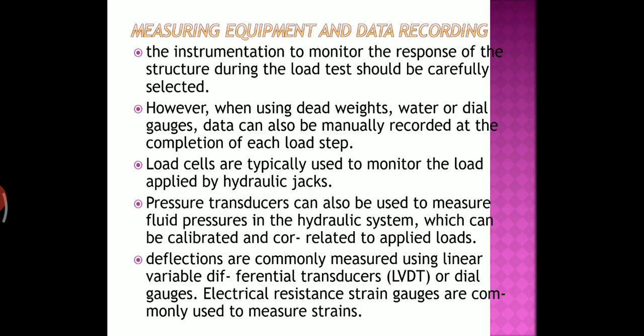In that case, the amount of load is recorded at the completion of each load step. Then load cells are typically used to monitor the load applied by the hydraulic jacks. With the use of hydraulic jacks and the reaction loads given to the structure, that can be measured with load cells. Pressure transducers can also be used to measure the fluid pressures in the hydraulic system, which can be calibrated and correlated to applied loads. Then deflections are commonly measured using the LVDT, that is, linear variable differential transducer.